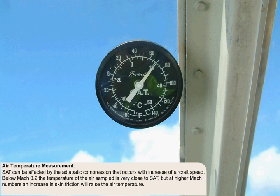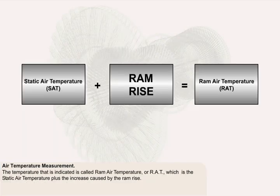Below 0.2 Mach, the temperature of the air sampled is very close to SAT, but at higher Mach numbers, an increase in skin friction will raise the air temperature. This increase in air temperature is commonly referred to as ram rise, and the temperature that's indicated is called ram air temperature, RAT, which is the static air temperature plus the increase caused by the ram rise.